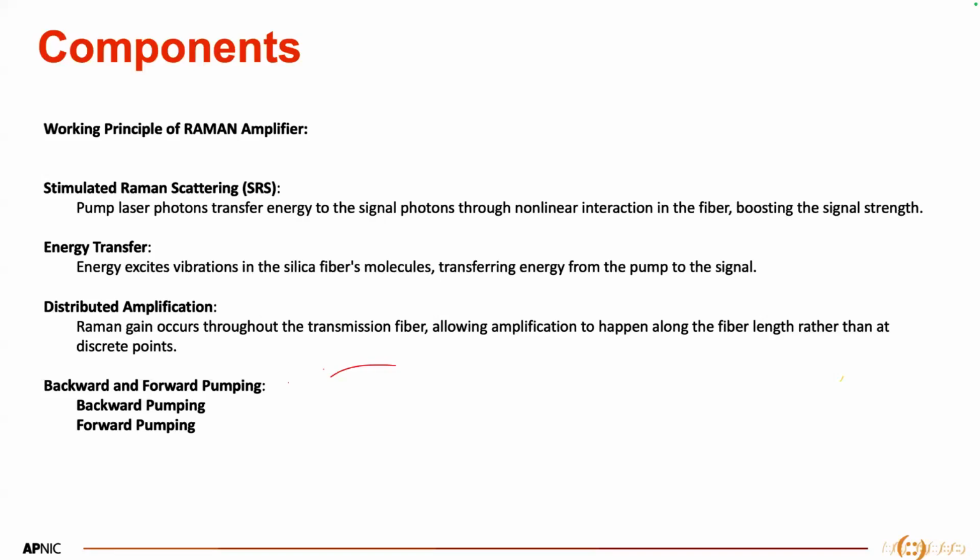It can be backward pumping, it can be forward pumping. Backward pumping means the laser is pumping from one point to another, and the pumping is working in the opposite direction of the signal. Forward pumping means the pumping is working with the signal in the same direction.